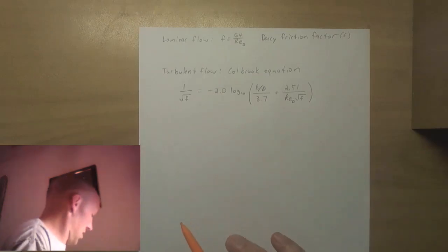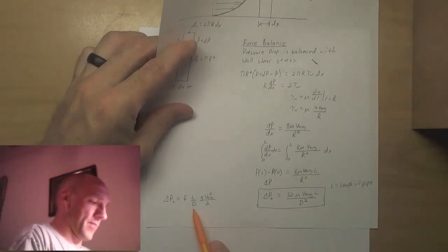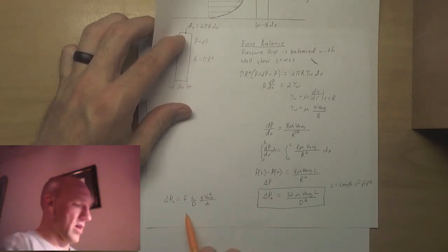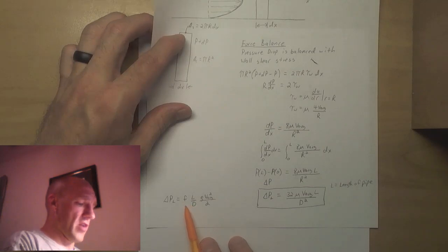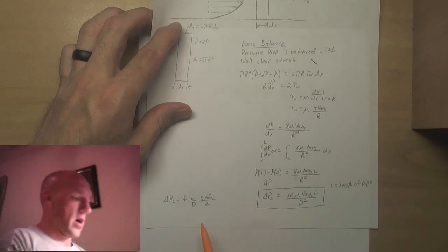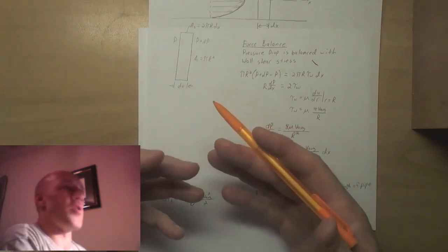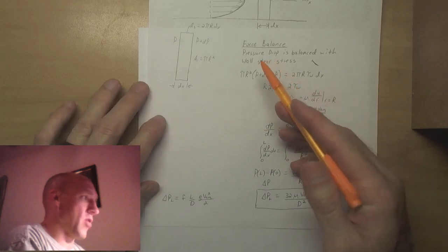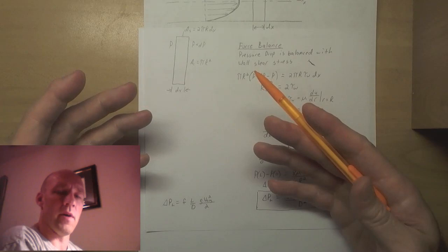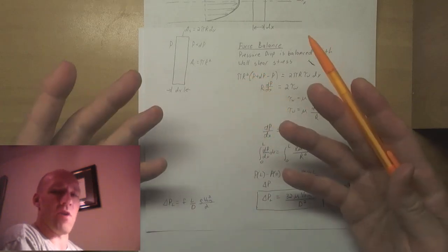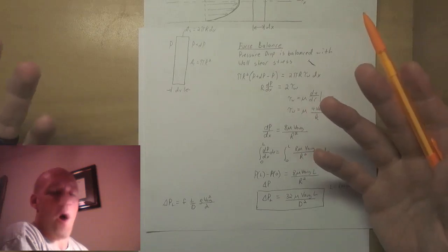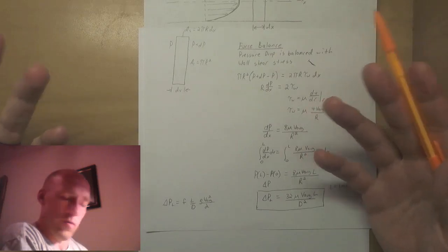So basically, you take this relationship through a process called non-dimensional analysis, which is really just rewriting standard equations in non-dimensional form. The reason you would want to do that is because maybe you do a bunch of experiments using a 1/4-inch tube, but we'd like to extrapolate this up to 2-foot diameter water pipes, running under the sewer or underneath the streets.